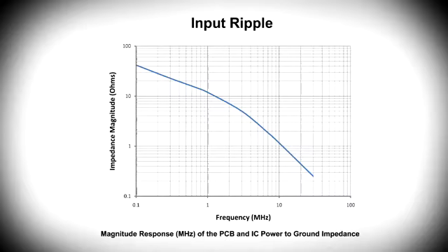As a matter of convention, the voltage of the input ripple should be constant at all frequencies. Because the supply circuit impedance isn't constant, we simply adjust the input power to maintain a constant input ripple voltage. The actual amplitude of the ripple should be set equal to what you expect to find in your system. For these measurements today, I will use 100 millivolts peak to peak at each frequency.